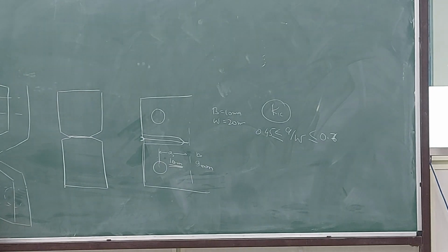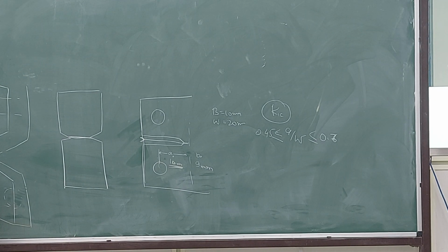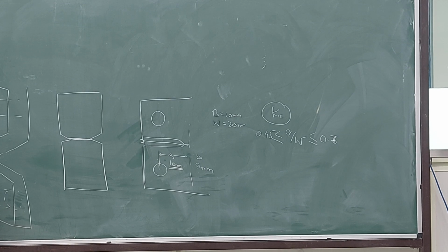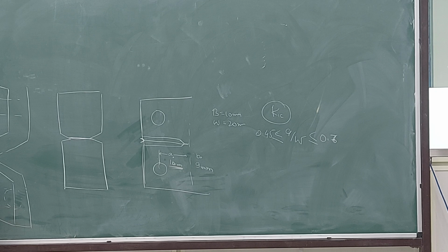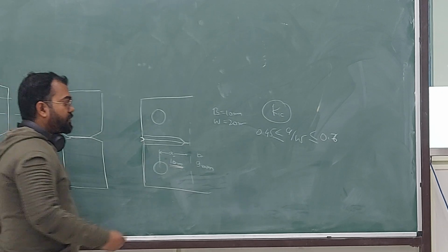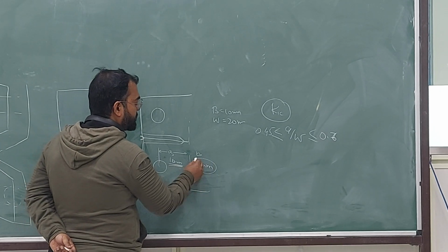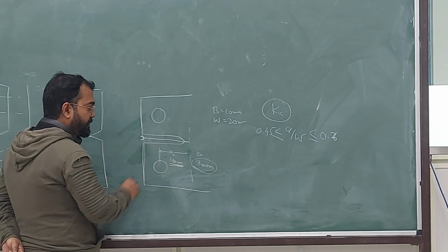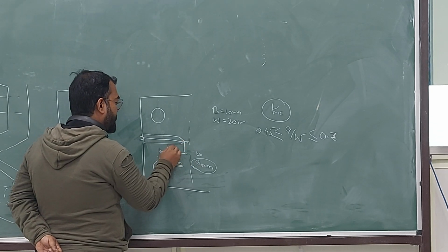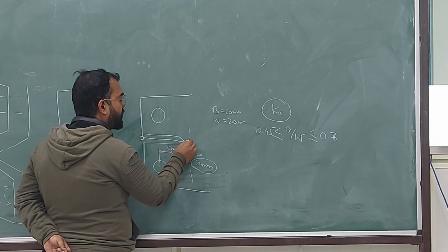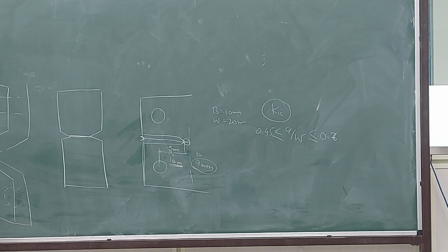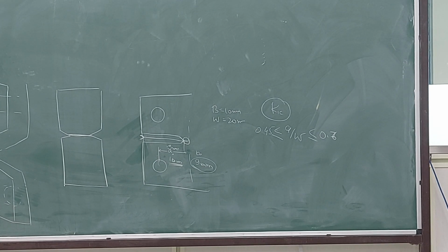That's your call, how much fatigue you want to do and how much fatigue you should do. Okay, so you will make an initial crack length of 9 millimeter, sorry, a notch of 9 millimeter. So this tip is at 9 millimeter, and then for 1 millimeter you will do fatigue cracking. Okay, that is called fatigue pre-cracking.